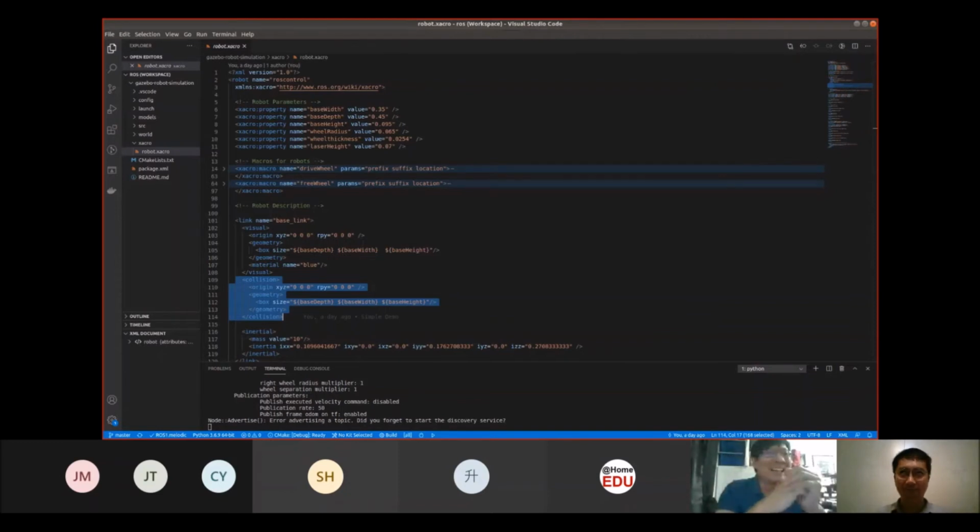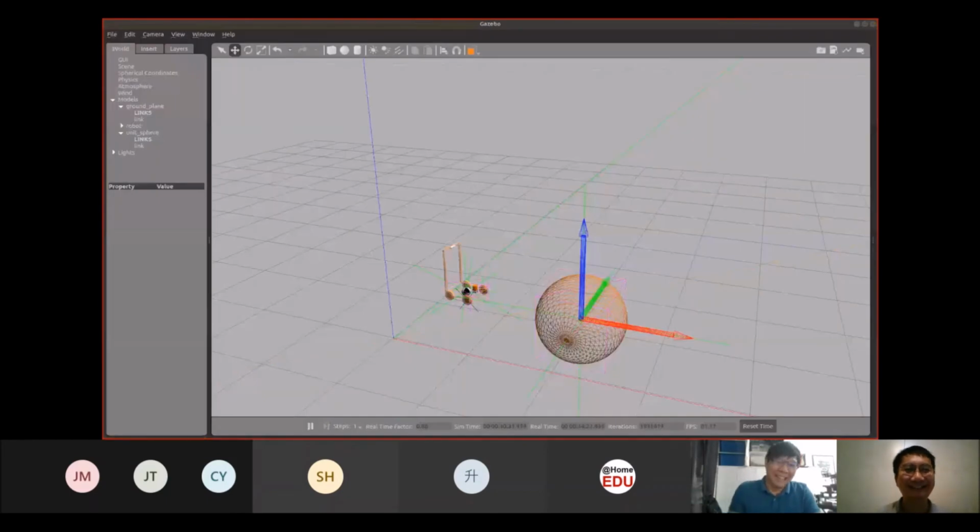I think ROS is using meters. Yes, ROS is using meters. So you have to open up the file and edit it manually. Under asset there's a unit over here. Instead of 1, you need to put 0.001, then it will work. I guess that is a very important experience, because it is not easy to detect this kind of error.